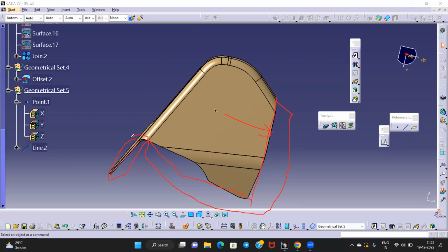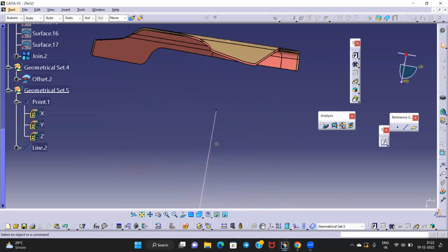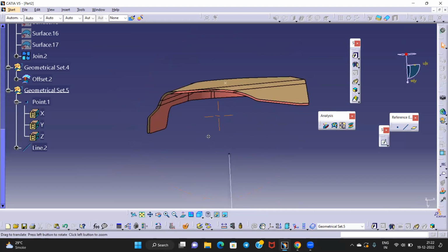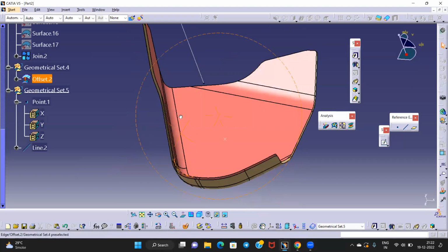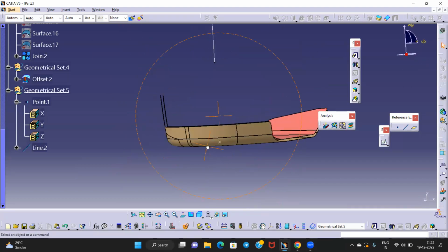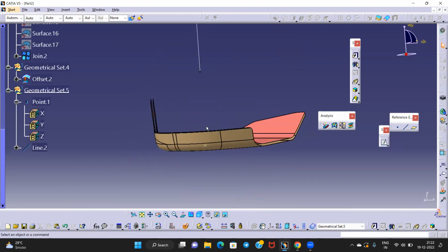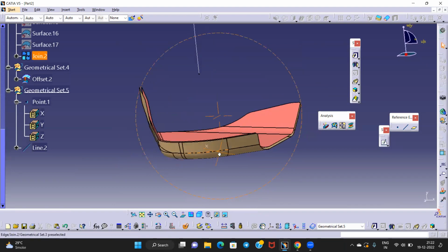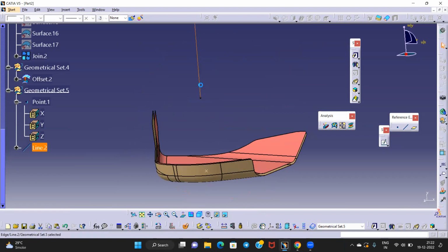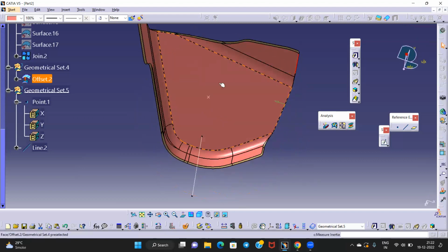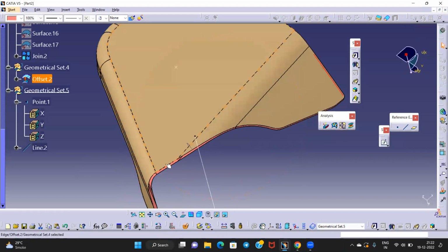So this comes in A surface. So don't think about this first. So this will be your draft direction, and rest of the things will make a 90 degree, no problem. Because if I'm keeping this as my die, this is my core, and this is my cavity, right? So for tooling direction, these faces are parallel. This face is parallel, but this face is perpendicular.